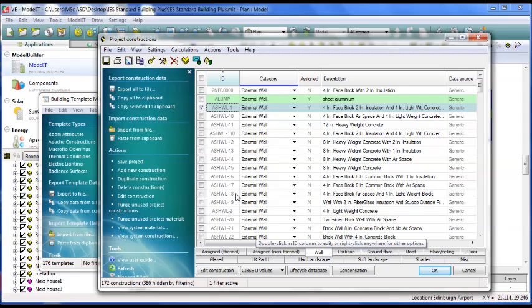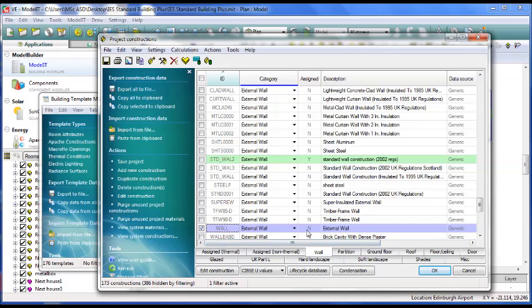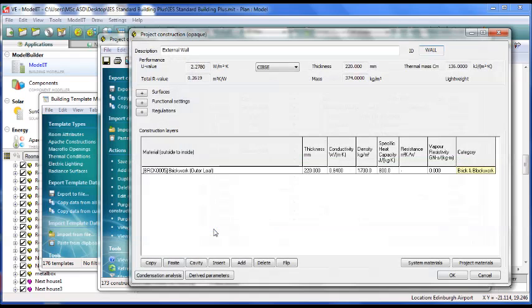You may want to start from absolute scratch and start adding things in, and the way to do that is to click on Add a New Construction. Remember we're in walls here, so it will call it wall, and it'll take the most basic wall construction it can think of, which in this case is a double layer of brick, or rather a single layer of 2 brick thick.